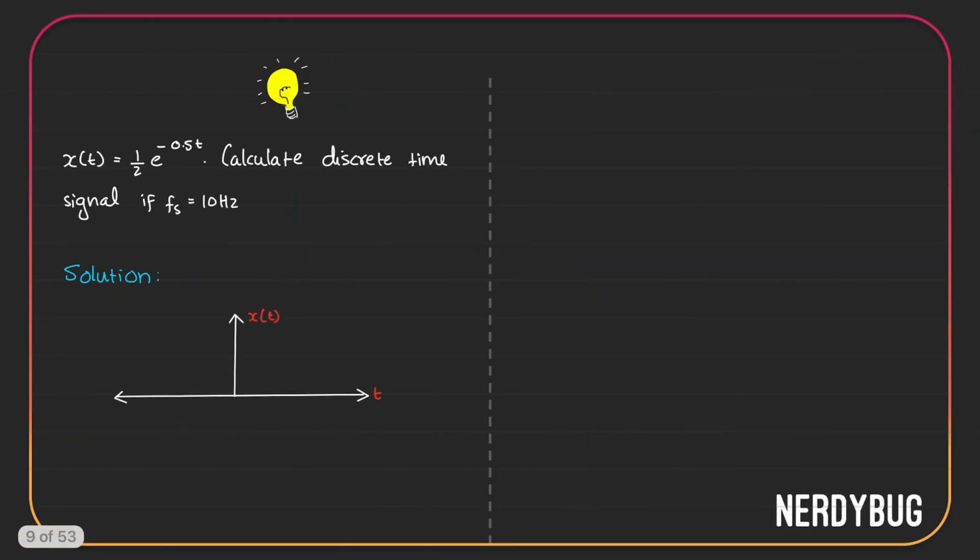How about we solve a problem now? The question is, x of t is given. X of t is half e to the power minus 0.5 t. And we have to calculate the discrete time signal if fs is 10 Hz. Here fs means sampling frequency, from which we can actually write the value of sampling time period. Ts will be 1 by fs, 1 by 10, so I can write 0.1 seconds.